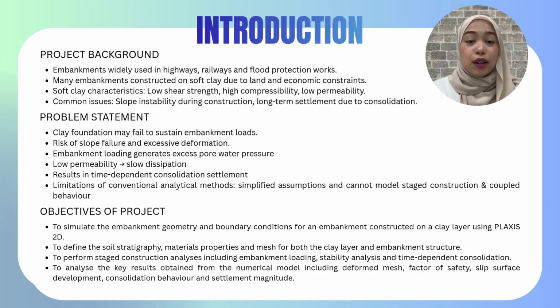Embankments are widely used in civil engineering projects such as highways, railways, and flood protection structures. They are often constructed over soft clay layers due to land constraints and economic considerations. However, soft clay soils are characterized by low shear strength, high compressibility, and low permeability, which can lead to stability problems and long-term settlements. When embankment loading is applied, the clay foundation may be unable to sustain the imposed stress, causing slope instability and excess pore water pressure.